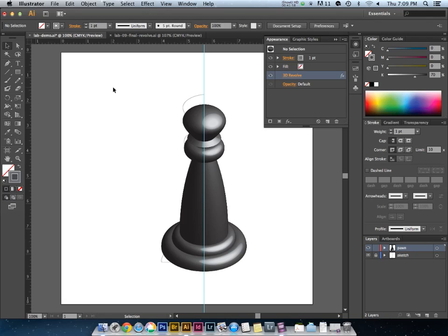A lot of people like to do flower pots and things like that using this tool. So do you always have to start with a half image to make it work? You do, because it's going to revolve around. I mean, you can work with a full shape image, but it's going to take that full shape image and revolve it around the entire shape. So, if you want to create something that looks three-dimensional, like a cylinder, or in this case a pond, you want to start with a half shape and revolve that half shape to create your object.